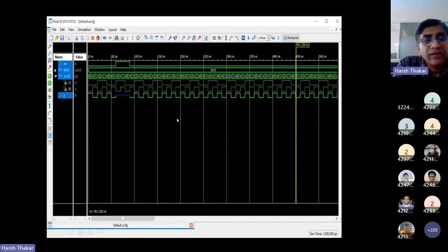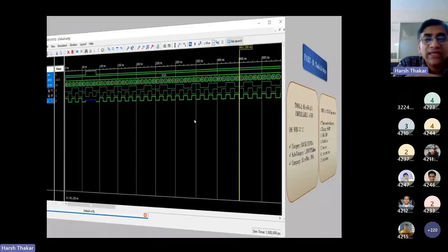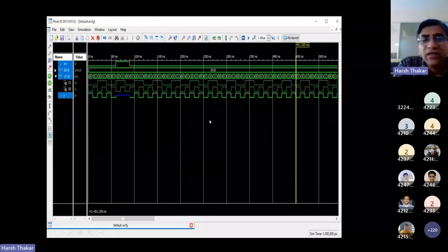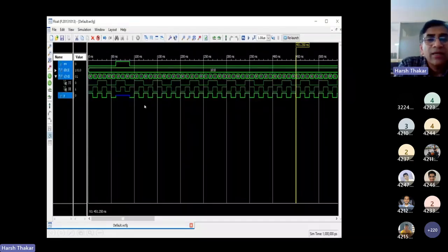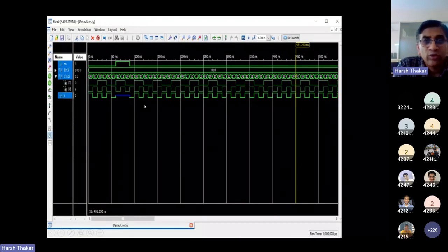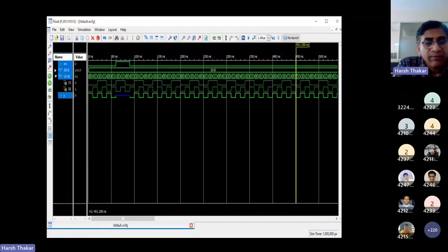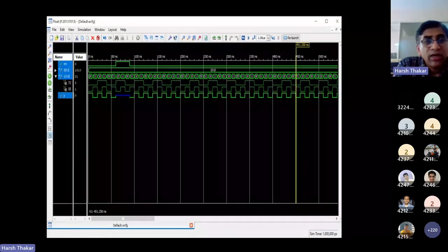So now, having done synthesis of the main VHDL model, having done simulation of the test bench VHDL model, we go to the last step of the assignment, which is called downloading. Okay. Now, downloading is a generic term. It's a layman term. What we call FPGA prototyping, right? So better we should use the words synthesize the main model, simulate the test bench model, and prototype the FPGA.